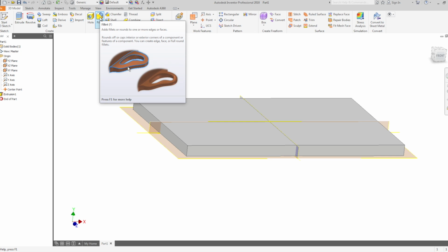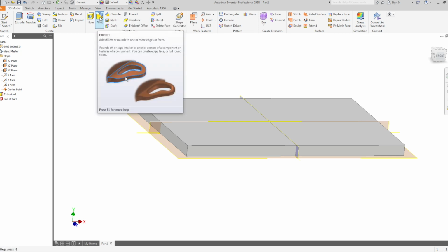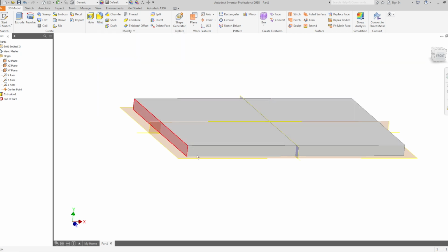You can also do inside corners and make them not sharp on the inside. But these fillet commands are easy to edit, update pretty easily, and I find when I try to make a rectangle in sketch mode with round corners, it's much harder to modify after.